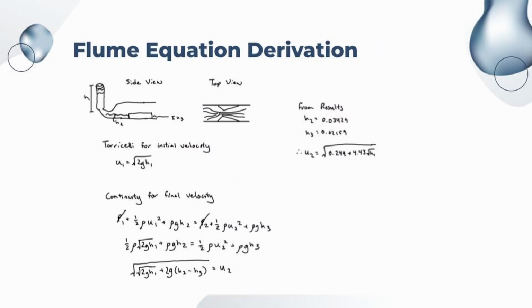One way to show the Venturi effect is through a Venturi Flume, which is a device that takes advantage of the Venturi effect to measure the flow rate of a liquid based on changes in an elevated section that causes pressure to drop. To measure flow rate, we need a measured pressure at an early point during the flow and at the constriction point. Having these pressures allows us to use key equations, which allows us to calculate the fluid velocity and flow rate at the point of constriction.